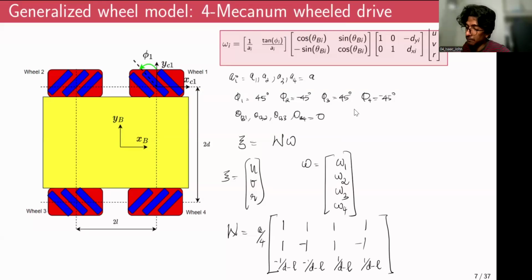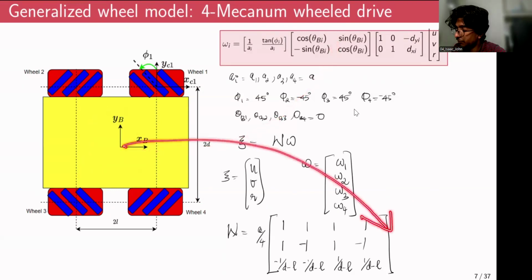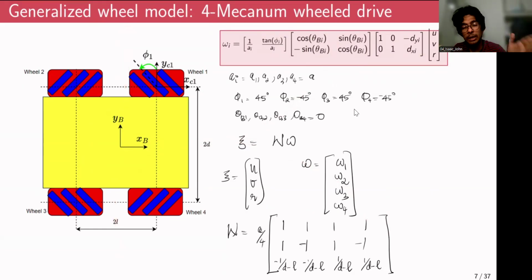All the elements are fully populated. So that basically gives this robot a very high degree of maneuverability, right? It can move in the forward direction, it can move in the backward direction. It can rotate about its own axis with zero turning radius. It can take a curve like this or like this with finite turning radius. Apart from that, it can go in the lateral direction, by keeping its orientation constant, it can simply slide left and right, just like that. It can also move diagonally like this, right?